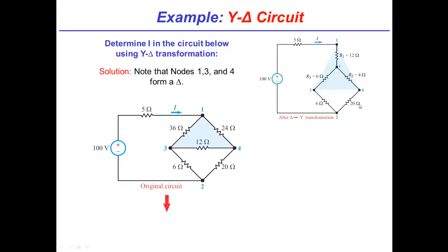And then put those in parallel, give me one resistor, and then again in series with the R1. So let's see, am I barking up the right solution? I think I am, right? You are, because what we basically do, as Michel said, is you end up with a 12 ohm resistor here, a 24 ohm resistor here. Then you can put those in parallel with each other and then put them in series with the 5 ohm resistor and the 12 ohm resistor. So then you end up with 25 total.